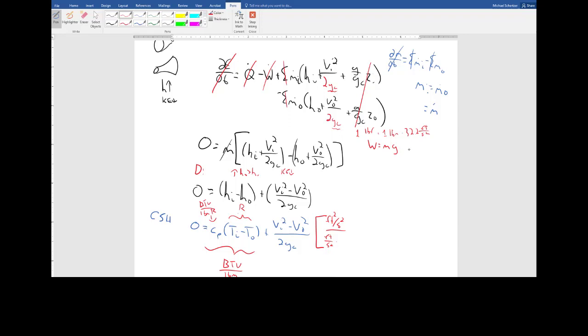Again, I'm not a mathematician, but I know that 1 doesn't equal 32. So instead, we have to take this and divide by gc. Now, what's gc? It's kind of like an acceleration, so it's 32.2. Its magnitude is the same as the gravitational acceleration here on Earth, so that would cancel out the feet per second squared and the 32.2.